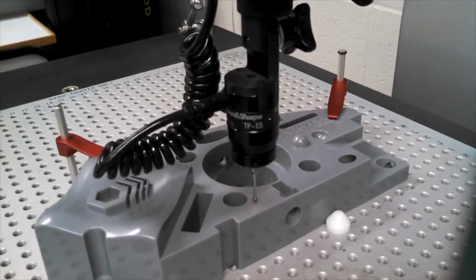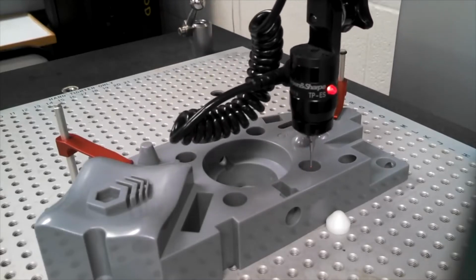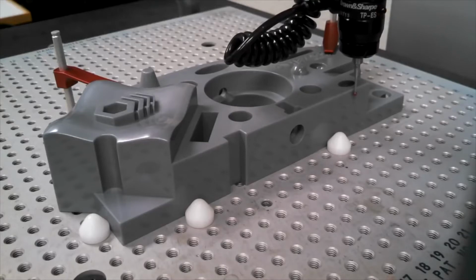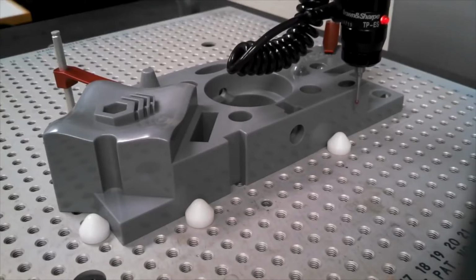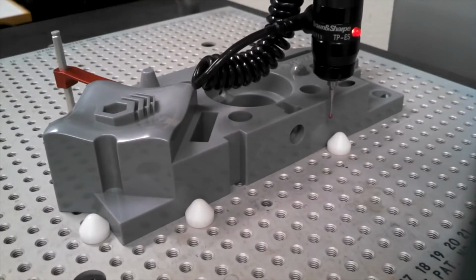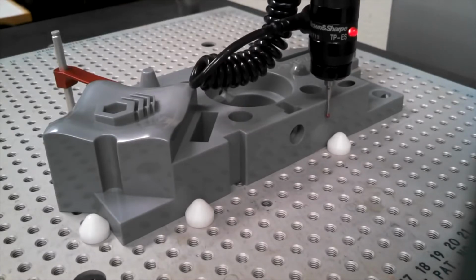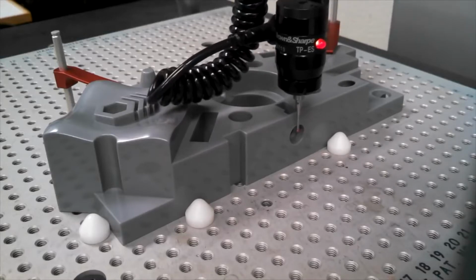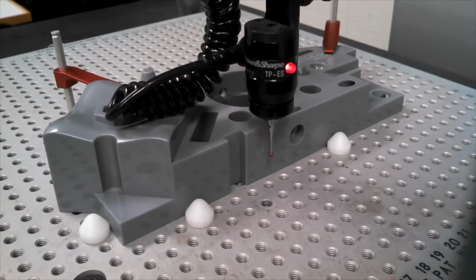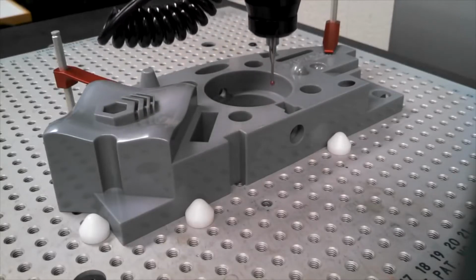When the probe contacts a particular location on the object, the machine samples the 3D position, thus measuring the location of one point of the object's surface as well as the three-dimensional vector of the measurement taken. The process is repeated as necessary, moving the probe each time to produce a point cloud, which describes the surface areas of interest.